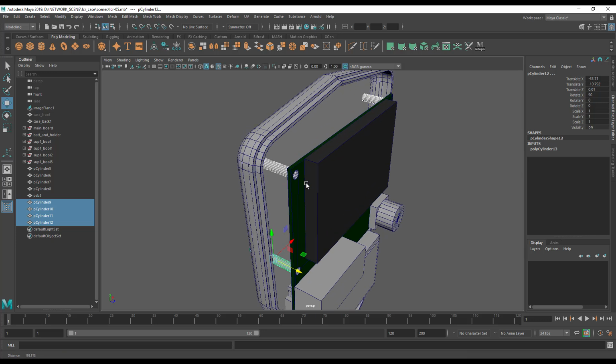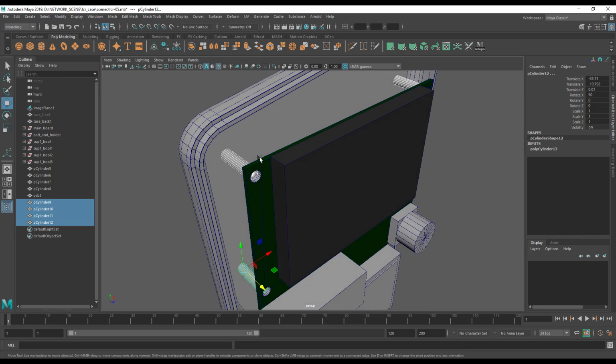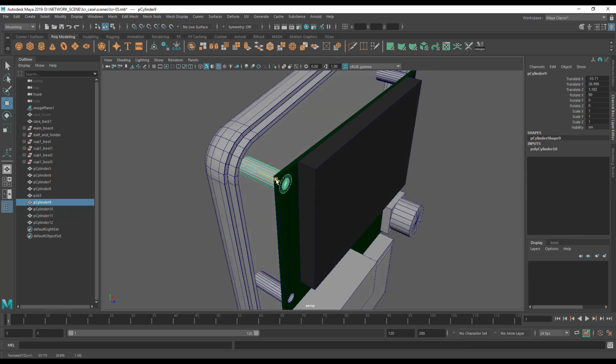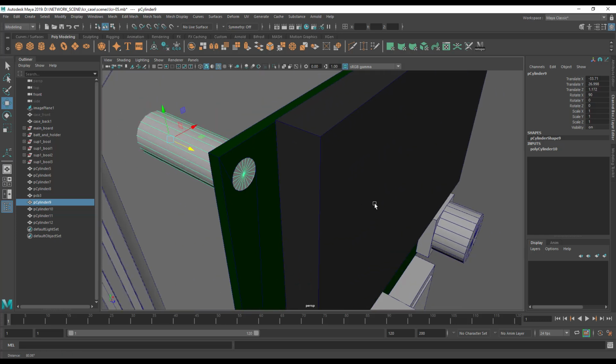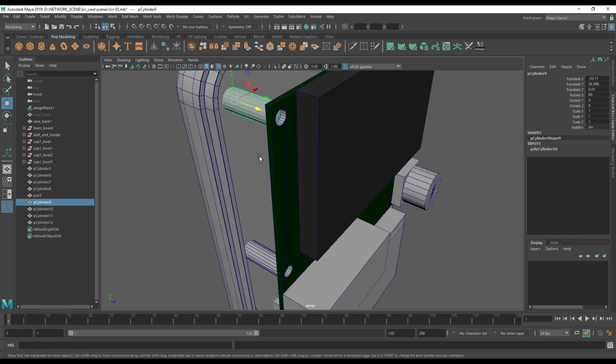So let's take these and let's make these a bit thicker, because they're going to get a hole through them which the screw needs to screw into. They also need to be able to support the circuit board, and they need to be thick enough that when we drill that hole through, we're not trying to support the pillar with 0.5 millimeter of material. So let's come in and we'll change this to 2.2 maybe, and you'll see they get a lot thicker. So if I move this one through, there's actually a lot more material here to support the circuit board, which is what we want, and there's probably enough material here to support having a screw hole through it as well.